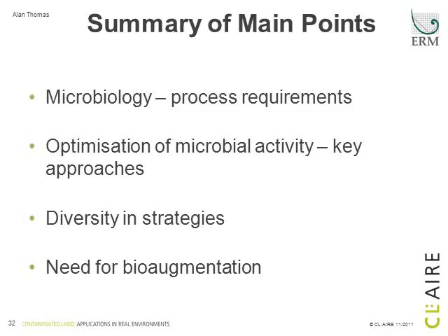And we've also considered this whole debate between biostimulation and bioaugmentation. Probably in summary, I'd say that we don't need bioaugmentation for hydrocarbon sites. For chlorinated solvent sites, it may very well be a potential benefit, but you would need to evaluate that on a site-specific basis.